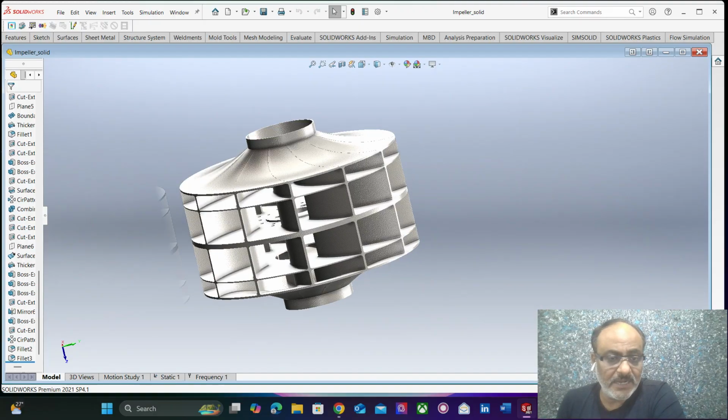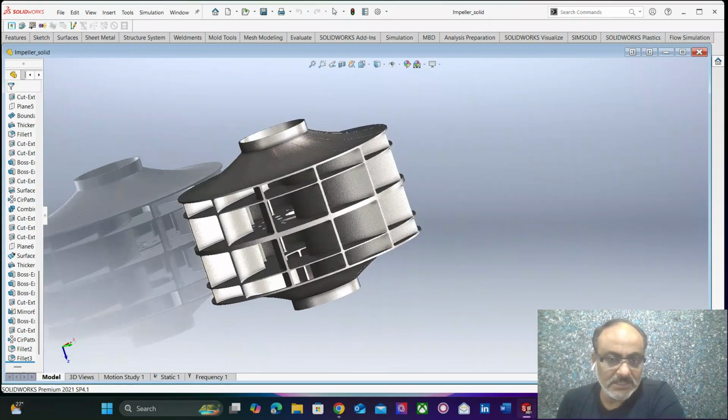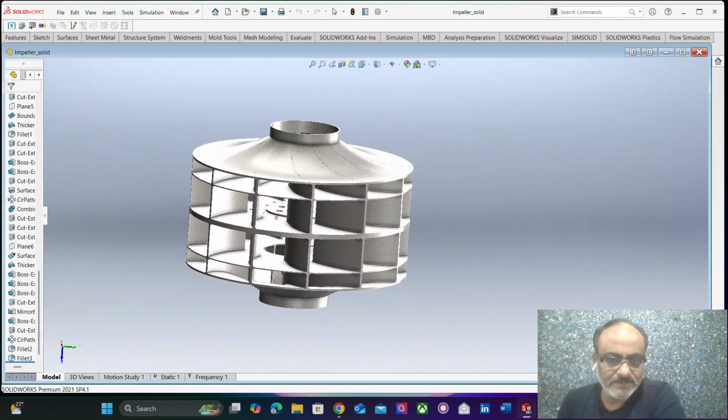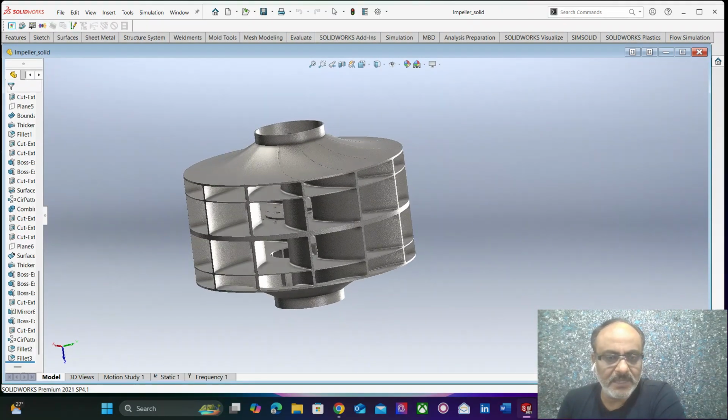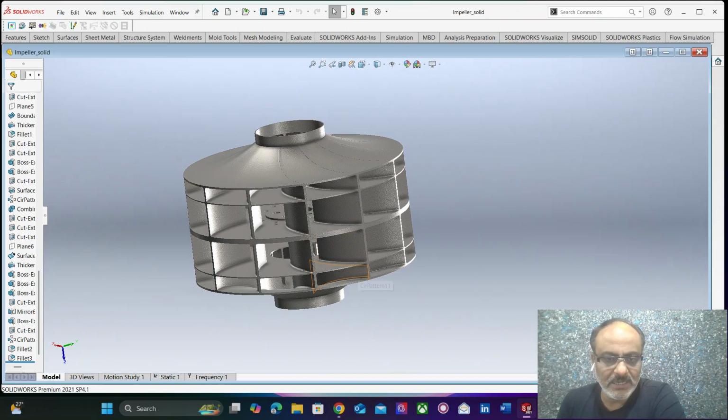The reason for that was, in the previous simulation, for that particular RPM of about 800 RPM, the blades, the vertical blades or vanes as we call them, buckled. So it had experienced both bending and shear failures.